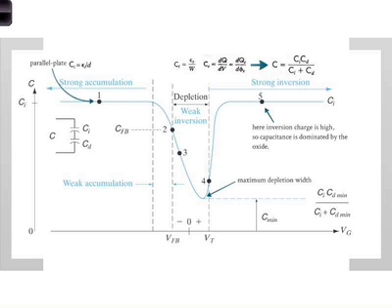Because it's a conductor, it's almost instantaneous, so you don't really worry about the speed that the charge is transferred back and forth. In our case, because we have a depletion region, it is not instantaneous. You expect some delay, and that delay means that the frequency of the signal determines the capacitance to some extent.